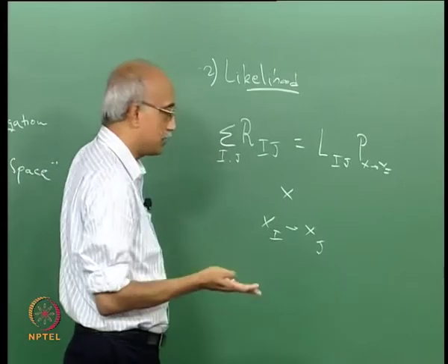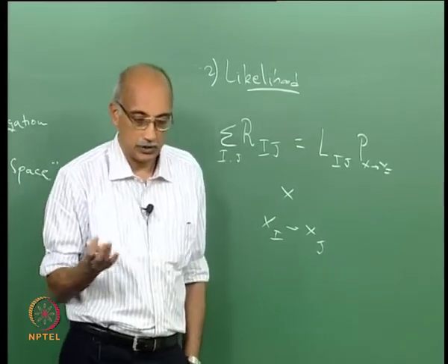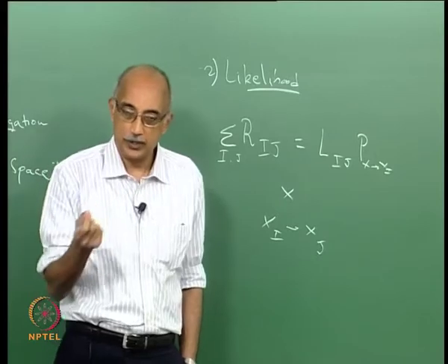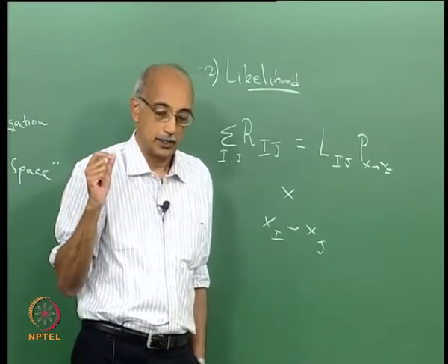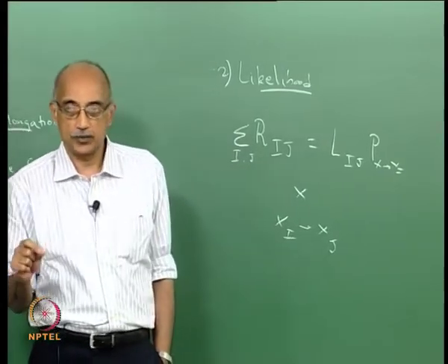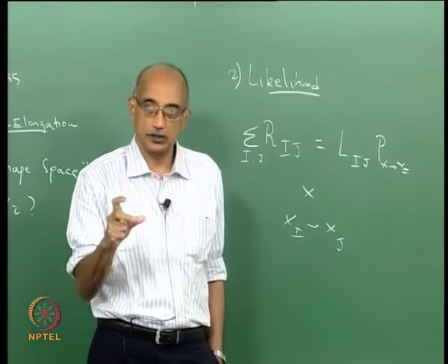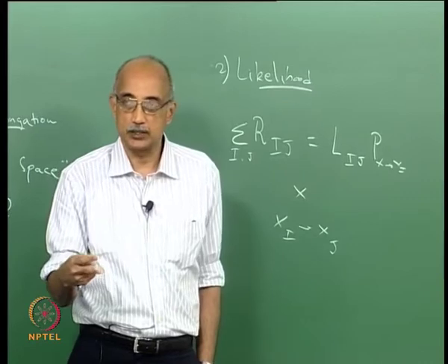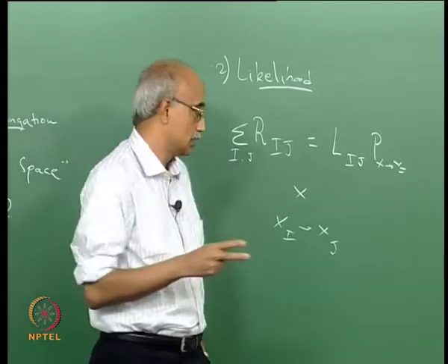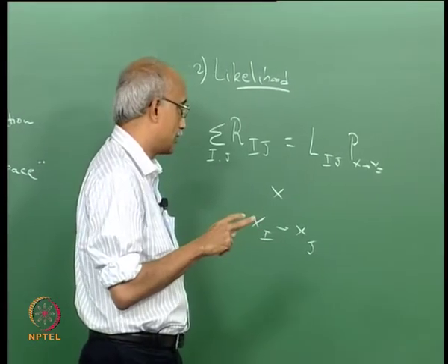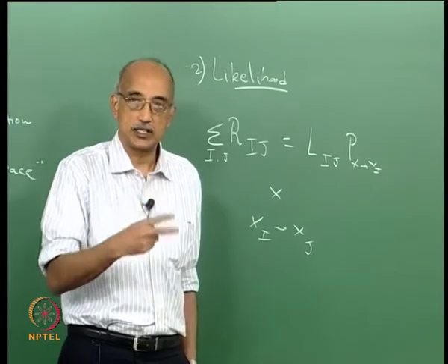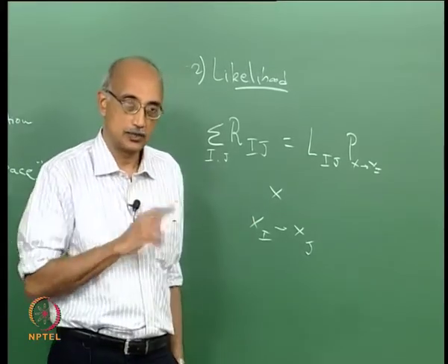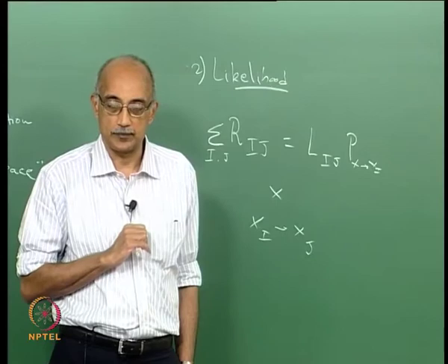So it is a probability based approach which takes into account again two things: the probability that the shape of the object or the shape of the particle belongs to a particular reference shape, the error that you make when you make that assumption, and the error associated in wrongly classifying it to belong to a particular shape.